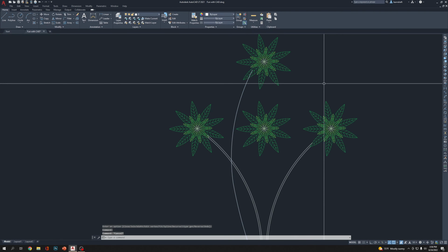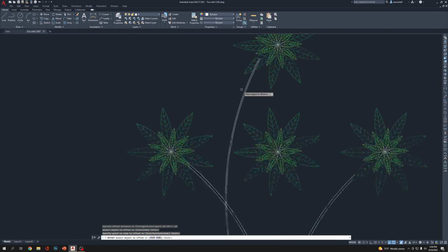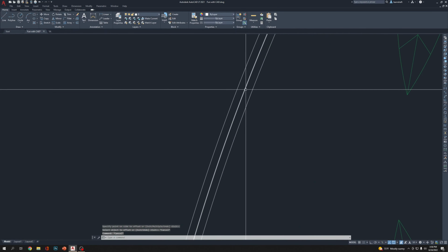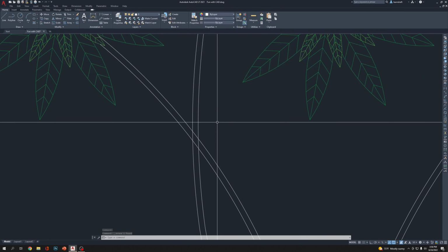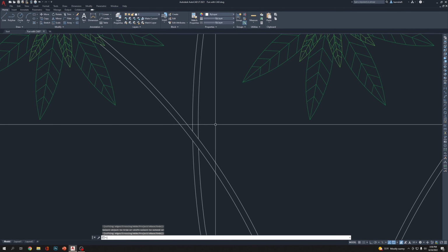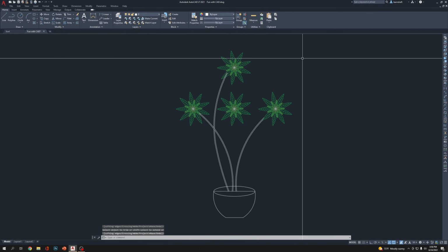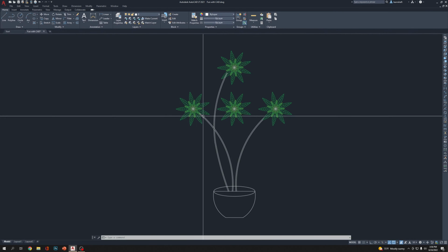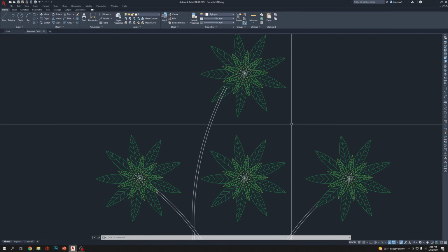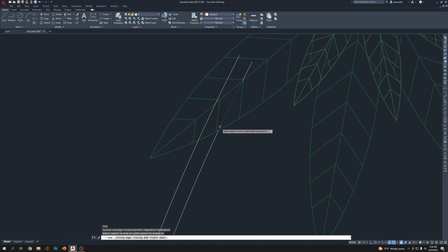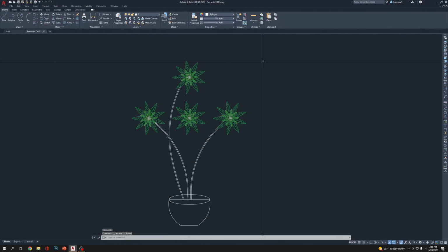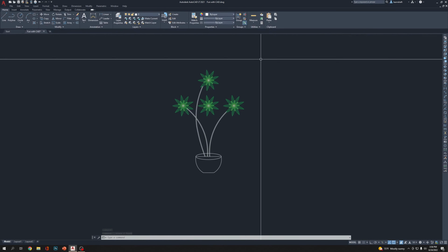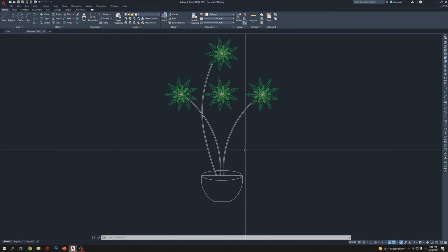One line becomes, okay, offset, enter, offset is 0.25, enter, click here, click inside, click here, click outside, press escape, select the center line, delete it, and then come here, trimming a long line, so it looks like that one goes first and this one goes second through the top, and then trim out the extra lines. So it becomes, yeah, and then